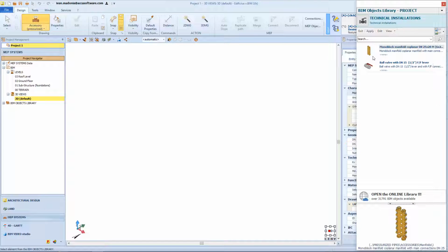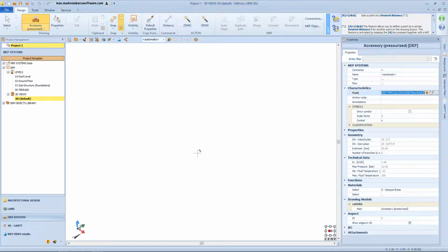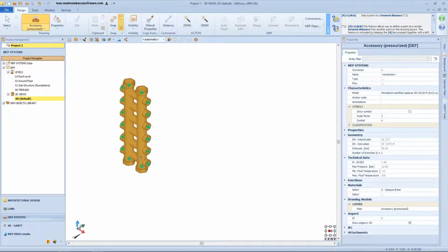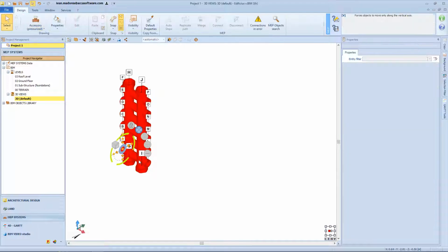By clicking on the button with the 3 dots from the model field and thus accessing the project library, the configured object appears here, in addition to any MEP objects previously created in the same folder, which remain in memory regardless of whether they are shown or not on the drawing. Working on the drawing, with the first click in any point the model is generated, with a second click the object is positioned on a point of the drawing, making use of the object grip support.